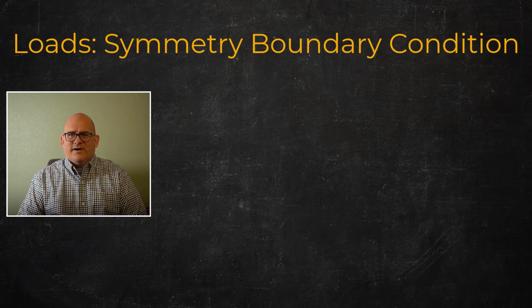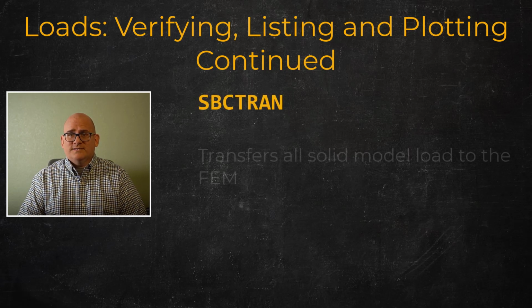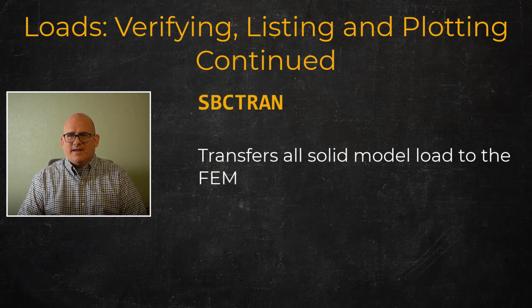Loads can be verified prior to solving by listing and plotting them. Only the loads associated with the current selected set of entities will be listed or plotted. As we noted before, solid model loads are not transferred to the FEM until solution. However, we can manually transfer them all at once with the SBCTRAN command. Individual loads can also be transferred, for example, FKTRAN, to transfer concentrated loads defined at key points to the corresponding nodes.